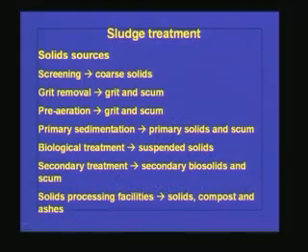So now we will discuss sludge treatment. What are the different ways we can handle the sludge, or what are the precautions we have to take while handling the sludge? Okay. So we will talk about sludge treatment. Nowadays sludge treatment is known as biosolids treatment. Sludge means something not useful or not desirable, that is the meaning of sludge. But once we call it biosolids, that means if we can give some treatment and get something which has a certain beneficial value, then we can call it biosolids.